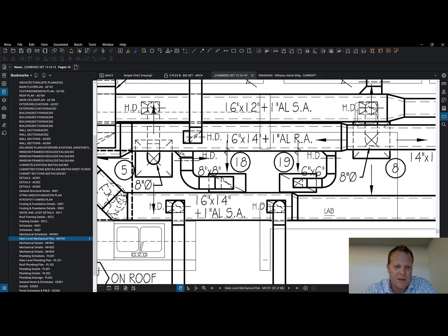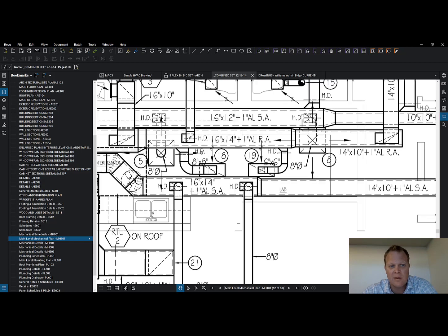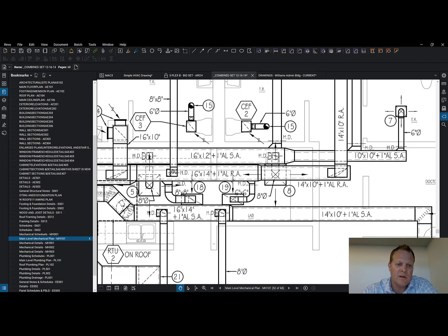And these little segments are just allowing the air to make the bend. This is straight section, 90 section, straight section, kind of like this section is the T into this return air trunk line. This one right here is just saying it's coming from above, I believe. But I have to go look at the drawing notes.